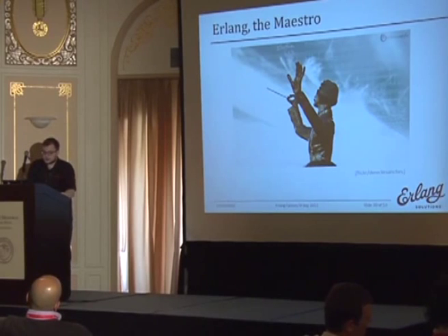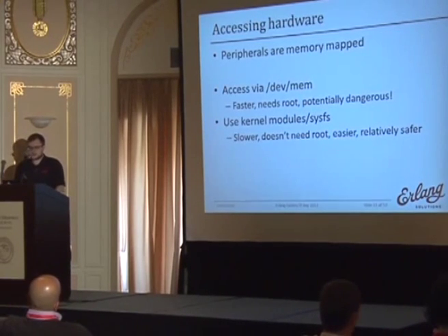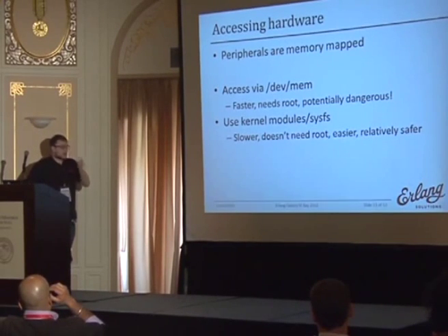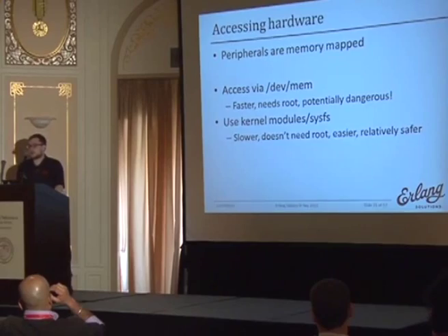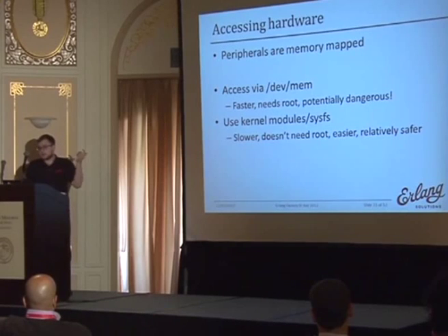OK, let's talk about hardware a little bit. On a traditional embedded Linux system, you have two methods of accessing hardware. Because these peripherals are generally, actually most of the time, memory mapped, you can just open /dev/mem. But this is, I'm sure you've done it before in your first computers when you're learning how to program, writing directly to the screen maybe, etc.